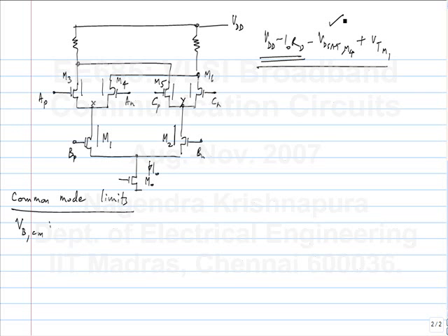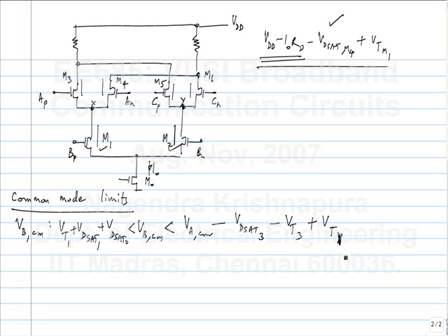It should depend upon common mode of A and C, right? Let's assume A and C are the same because they are the same logic level. Okay. The minimum voltage at X and Y should be such that a minimum voltage, it is related to the minimum voltage at X and Y and the maximum voltage at B. Okay. The maximum voltage at B is such that when X and Y are at their minimum, these two are still in saturation. Okay. So first limit was, okay, this is just the lower limit, and what is the upper limit now?